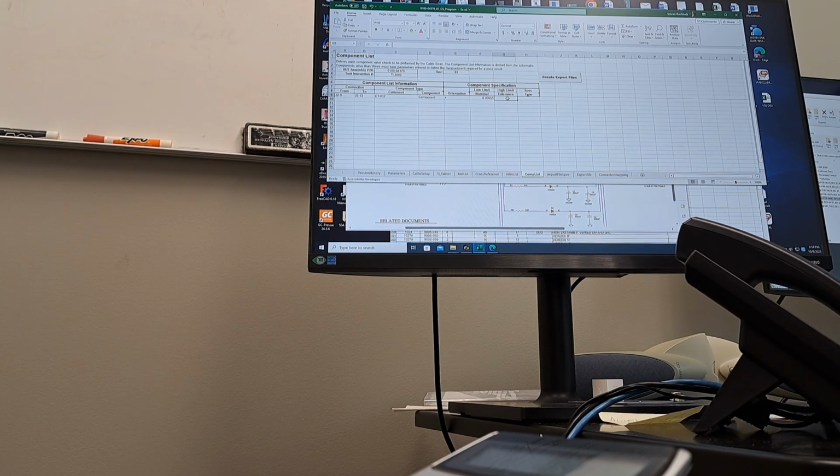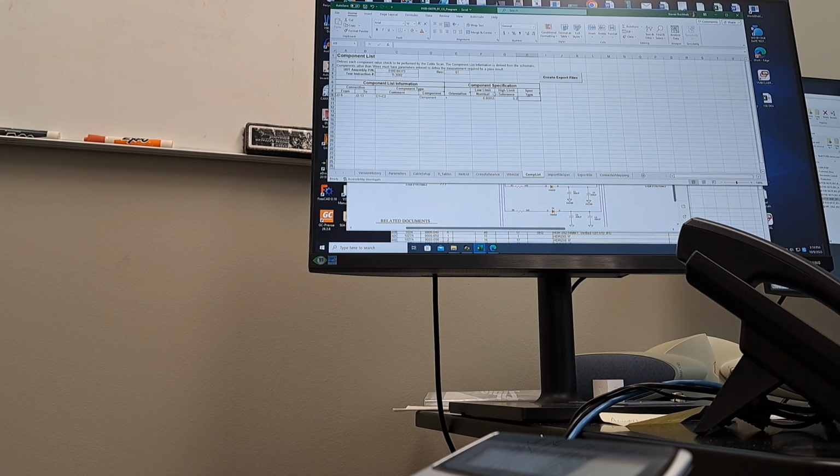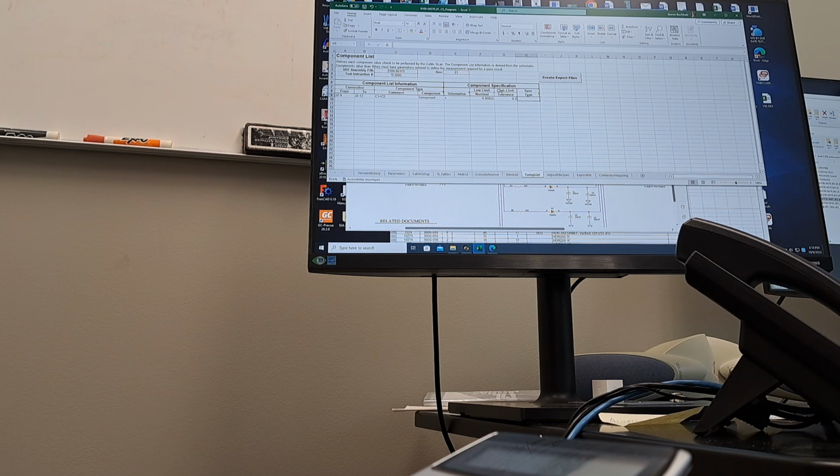But so let's just put in 20%, and then here, so you can put things in. Notice here, there's two things. It says you can have a low limit, high limit. So you could put the min max values in here if you want. Or you can put a nominal with a tolerance, okay? So low limit, high limit, that's a range. And then nominal tolerance, that's a tolerance.